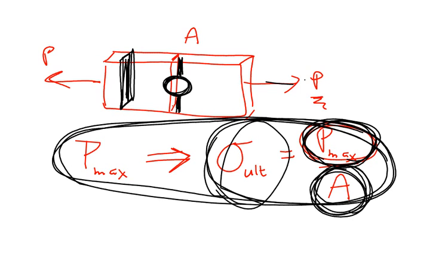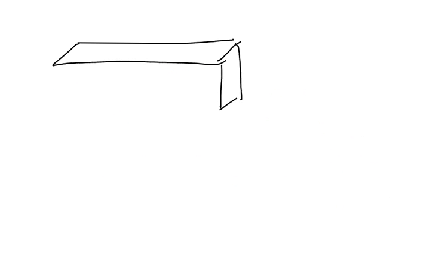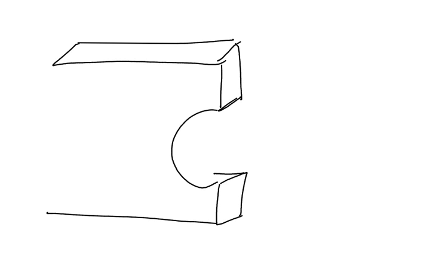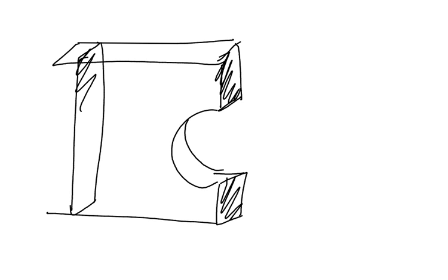Let me see if I can draw that a little better. Right at the center of that hole, if I were to make a cut, the area is this plus this, as opposed to the whole solid rectangle. So this area is smaller than that area. If I'm applying the same force P, then this is going to give me the larger stress.